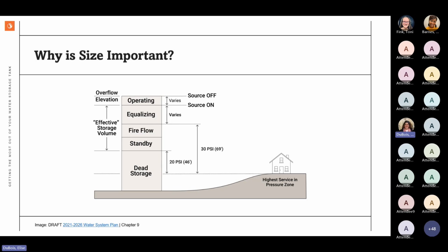And for the life of me, I can't think of the name of the stuff, but it's typical of a Type 2 tank. So it's that shotcrete coating on the exterior. We don't like to damage that because that allows damage to continue to bore in as it weathers over time. And that can in turn damage the steel, the rebar inside your concrete tank.